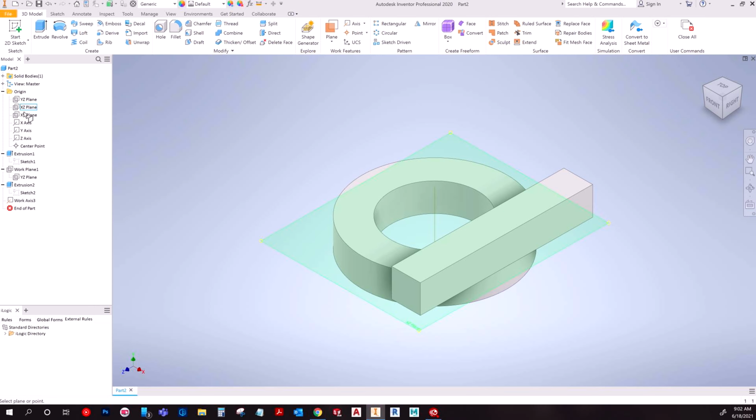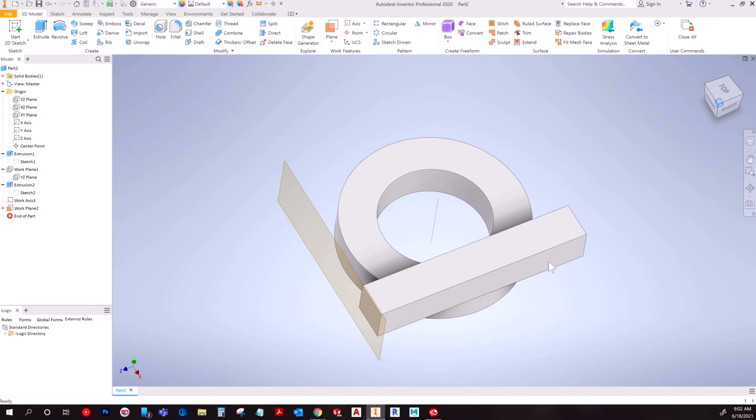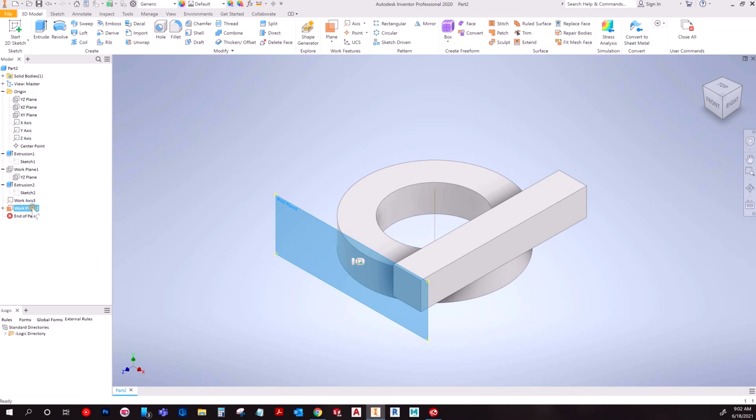I'm going to choose the XY, and then I'm going to choose this corner point right here. Now, granted, you could have done many other things, but if you want to quickly do a plane on a face, you could just do something like that, which, now it's perfectly aligned, as you can see. And then, like I mentioned before, make sure you're auto resizing these things. You can always just make as many as you need and then change it after. So that one's pretty straightforward.